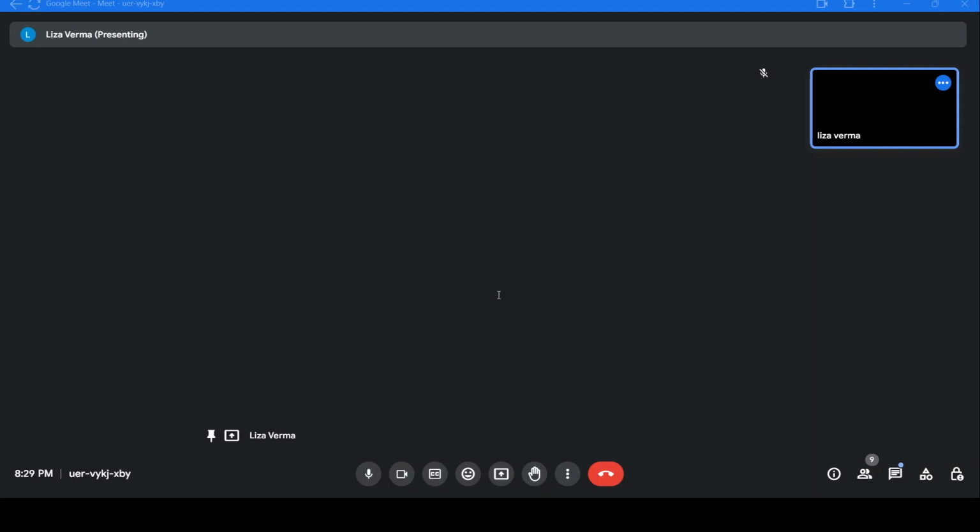And so the very first instruction can be written like this. If you take the memory locations as 0000 to FFFF, the very first location, the zeroth location, I can have a return. And the call can be say in 8000 where my main program is, or where I want to call any sub program. So logically, I can have a return before my first call instruction. Okay. So the question was which one is false?